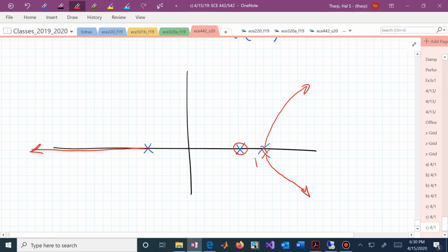So the PI controller actually is going to immediately force us into an unstable situation. And now the PID controller, that puts a pole there, and if we just canceled that by the other 0, we're still in the condition that we had for the PI.